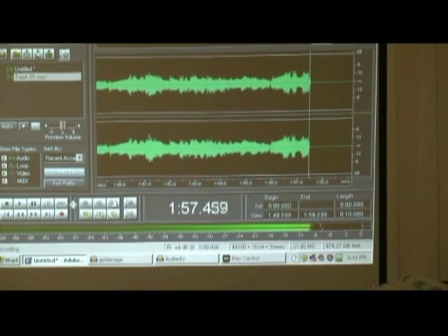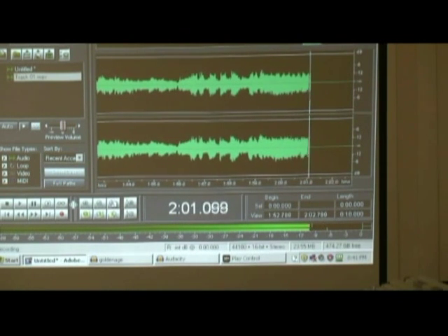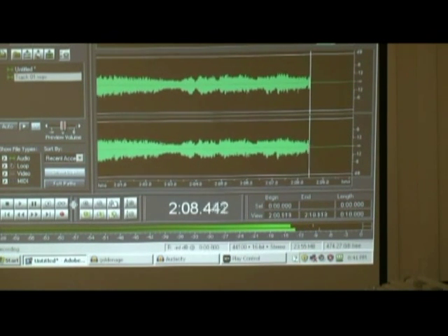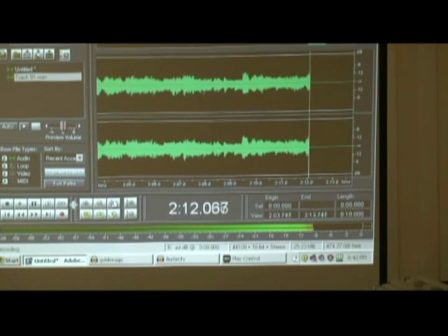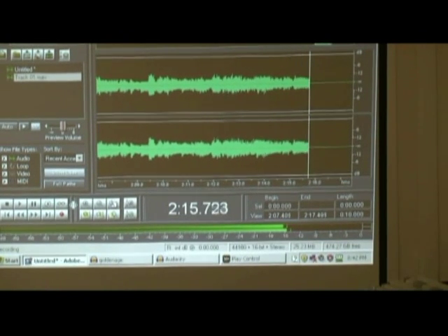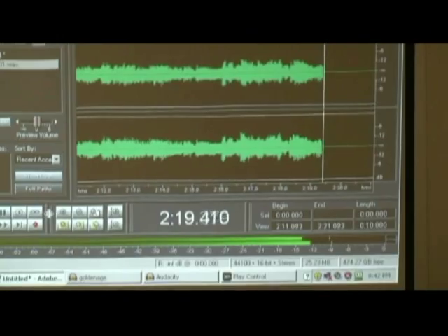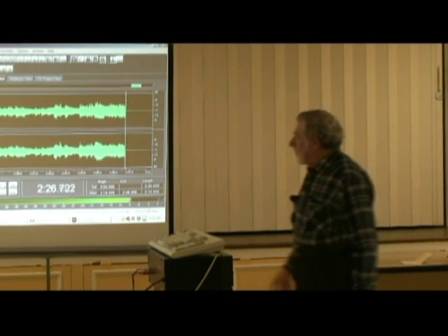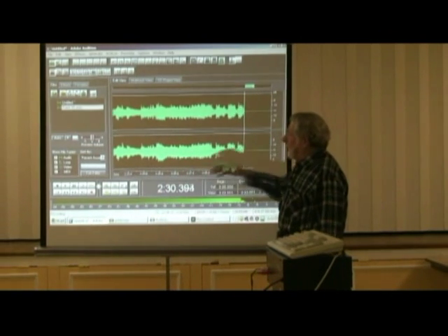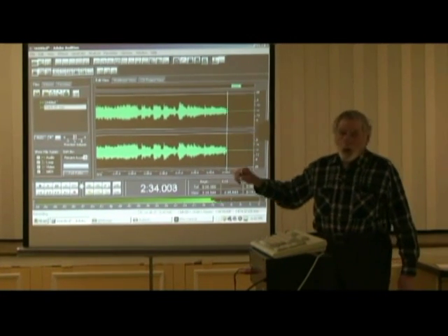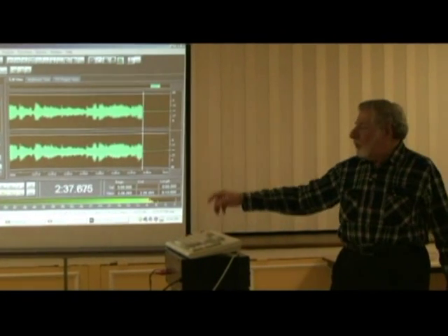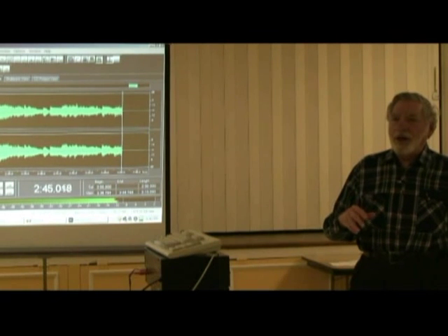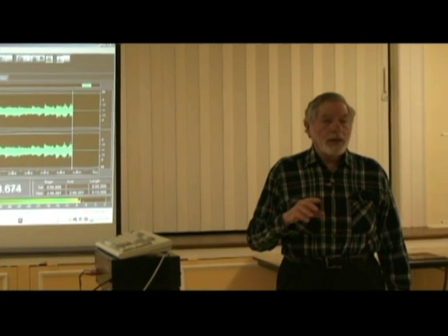The thing about digital, with an audio recording, with audio tape, you have the noise of the tape, the surface noise. With a record, you have the surface noise of the record, and that's the signal-to-noise ratio. Over the years I've forgotten those figures. It used to be about 20 or 30 dBs, I think, for the analog. With digital, it can be about 100 dBs. It's incredible. With digital, there's no noise level. You can be recording way down here, and later you can bring that volume up, and there's nothing below it that comes up with it. You do that with an audio tape, you record way down at a low level, and you bring the volume up, suddenly you hear all this hiss of the tape. But you don't get that with a digital recording, which means you have a lot more flexibility in that respect.